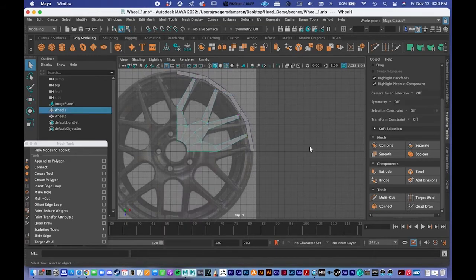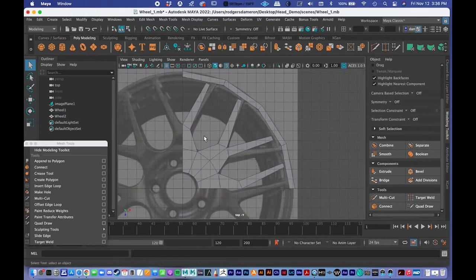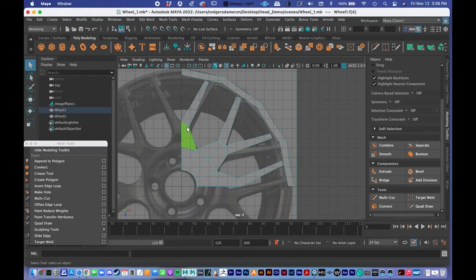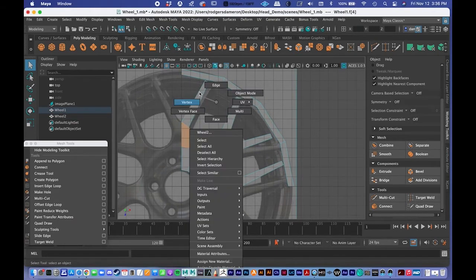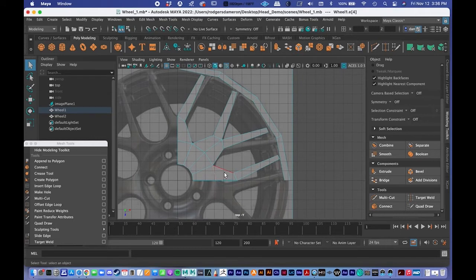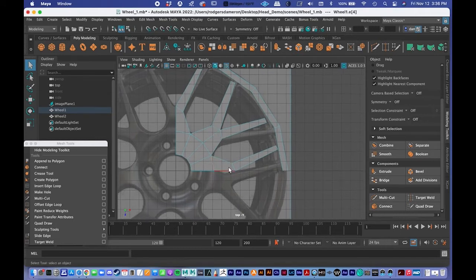So you can see here what I've done with the model. We had this pipe, which we cut into a quarter, and we have this pipe, which we cut into a quarter, and then on the inner pipe, I extruded this edge right here, and made sure for this first extrusion, making this face right here, that I did it in world rather than local. Same thing at the bottom. I extruded this edge down here, made sure that it was world rather than local when I extruded, by pressing that power button in the top right of the extrude tool. And then extruded that out.